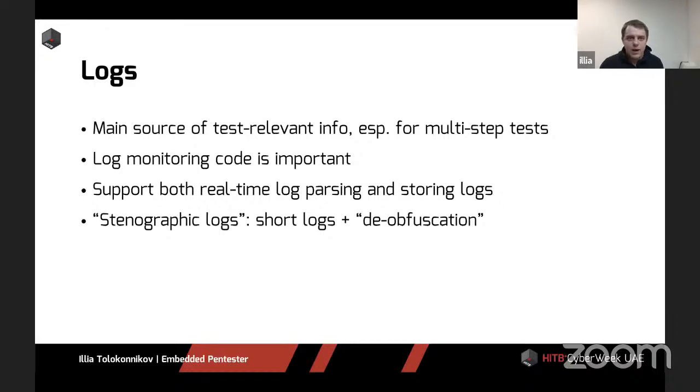One problem that we ran into trying to extend our logging on real-time OS devices is that when you start to improve your device and add new functionality to it, it eats into the RAM, and some devices have really low RAM or a low amount of flash storage. The first thing you want as a developer to cut to fit your new functionality is the logging verbosity. The problem is when your tests rely on those logging verbosities, and we're talking about trace levels a lot of times, you need to figure out a trick of how to save those logs so you don't just throw away your tests, because sometimes it's impossible to create a test without trace level logging.